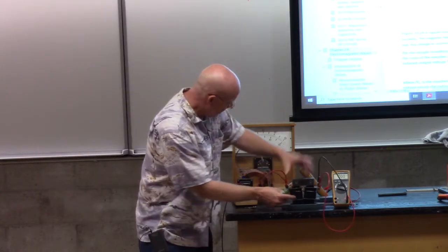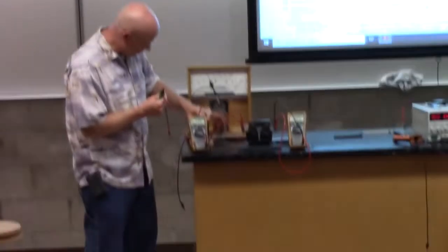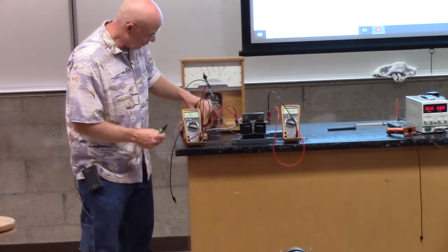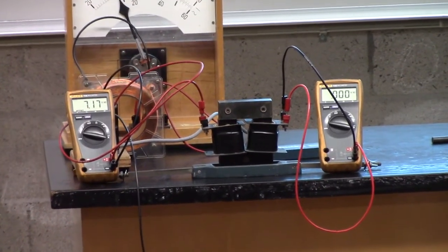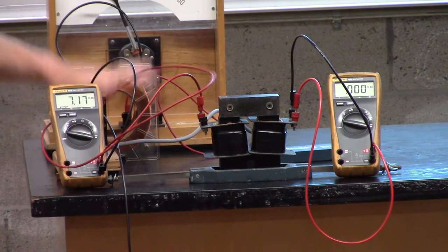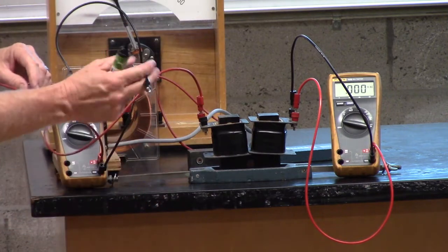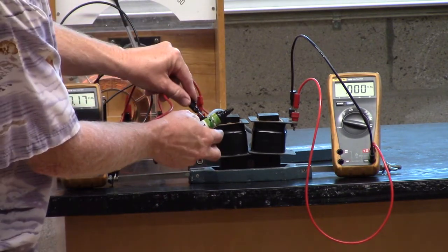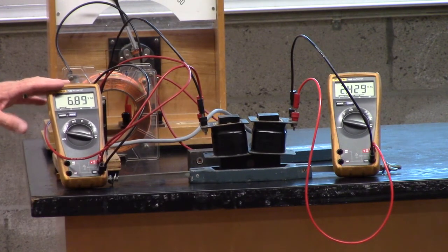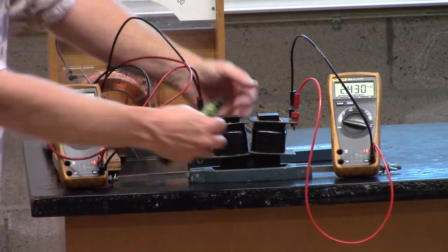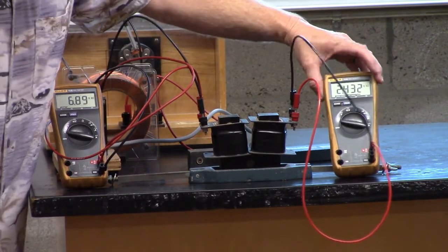So I will illustrate it here by saying, all right, let me take a voltmeter. Let me plug in the voltmeter to my primary. And I will just say right now, this primary is giving me 7 volts. If you want to see me plug it in here, you'll see it drop a little bit, but it's still close to 7. But see, now this is making some flux, and the flux is going from the primary into the secondary, and that should be producing some voltage here. And sure enough, this voltmeter says 2.4.